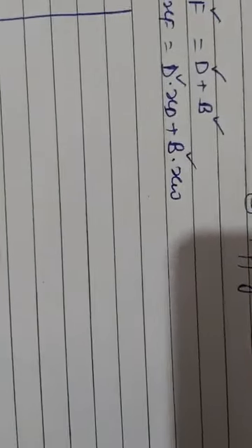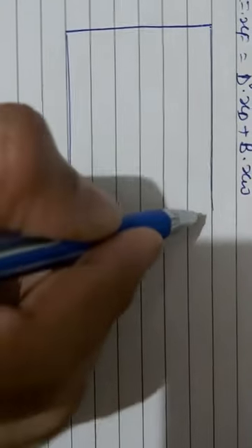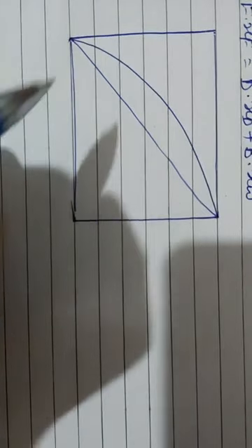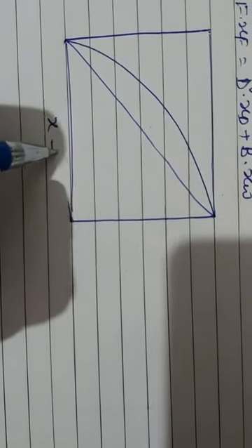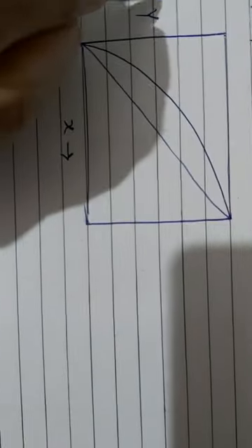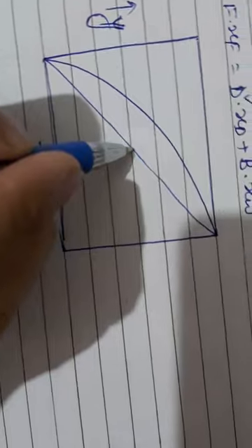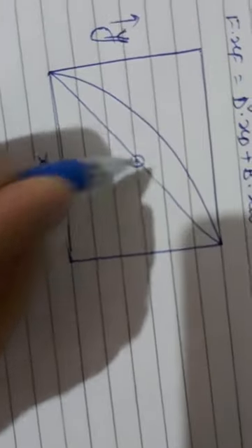So just a revision of the McCabe-Thiele method. First you have an XY plot. This is X, liquid composition, mole fraction. This is Y, mole fraction. Okay. So you first look at the feed point. You look at the feed slope.